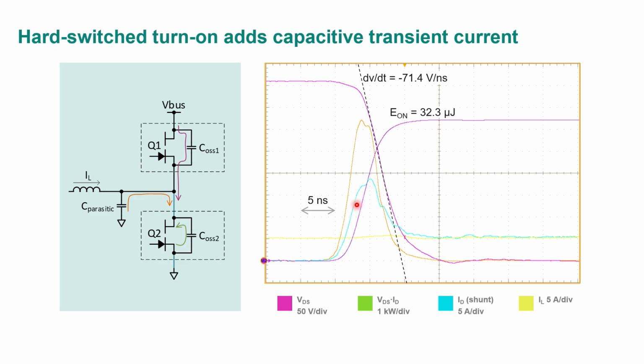In other words, you end up not hitting this peak, and the transistor will just slow down because it's approaching its own saturation. But you have to think about this: I'm discharging parasitic capacitance in my inductor, in my PCB layout, plus I'm discharging the capacitance of the opposite transistor. Those currents are what's summing into the transistor itself.